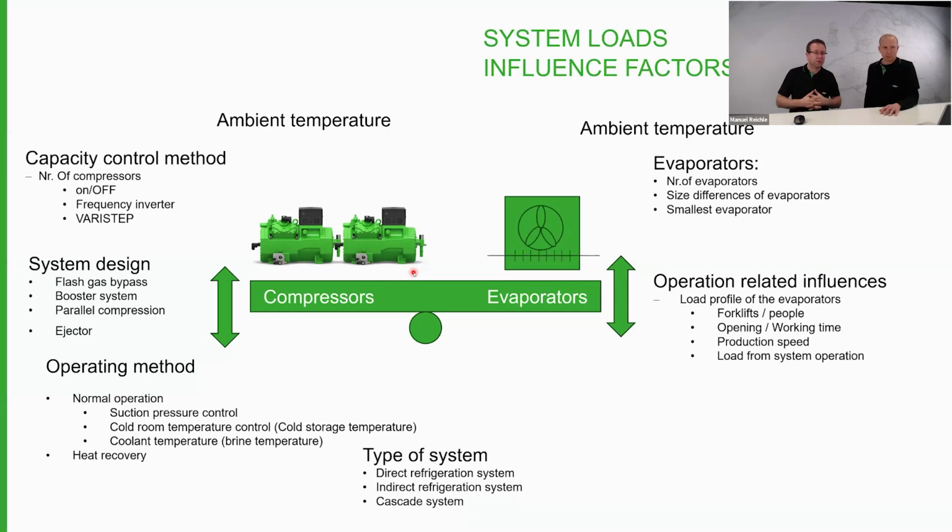Parallel compression, then we basically have to see it as 2 scales. So the MT compressor has an own scale and the parallel compressor have an own scale. Of course, the influencing is always a little bit the evaporator load plus the ambient, for example. So try to have both scales balanced is the challenge. The ejector brings the scales again into movement. So how accurate I can adjust the capacity, and I should do it without having any jumps in between. This is then the point for the rack systems where we'll have later some further slides.